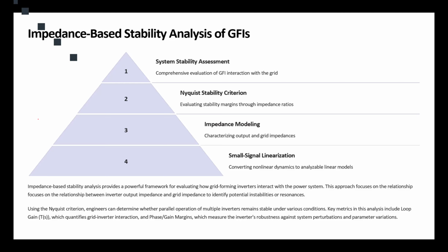That dynamic impedance would have a transfer function like all the other impedances. The transfer function of the inductance is Ls, correct? Or for capacitance it is 1 over Cs. Or for resistance, it is the resistance itself. So it's the Laplace transform of those impedances.